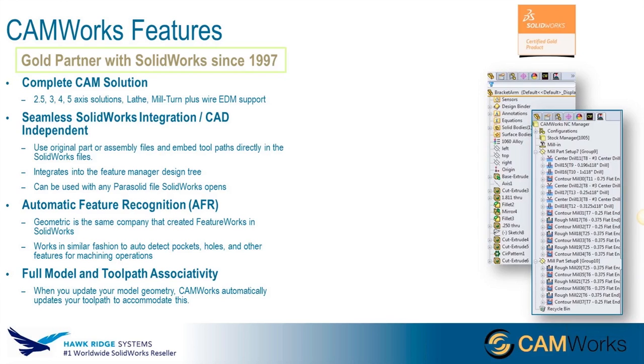So if you've got a front turret, a rear turret, main spindle, sub-spindle, or B-axis head that kicks over, all that sort of stuff, we can program those, as well as wire EDM support for 2 and 4 axis wire EDM. So if you've got tapers and stuff like that, we do offer that to be able to program.